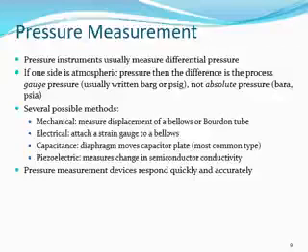Okay, now we will start pressure measurement. Pressure instruments usually measure differential pressure. When we need to measure the pressure, we should have two points. One is a reference point and the other one is a point that needs to be measured.